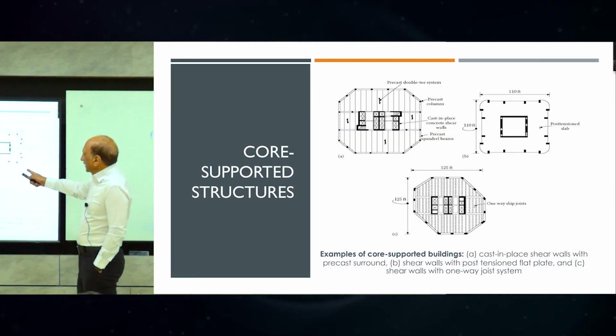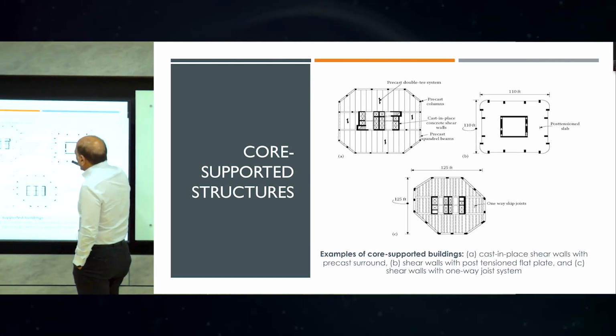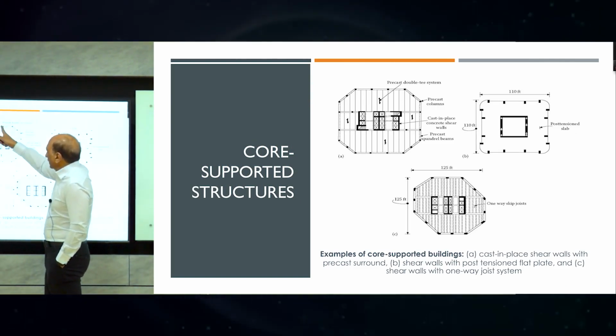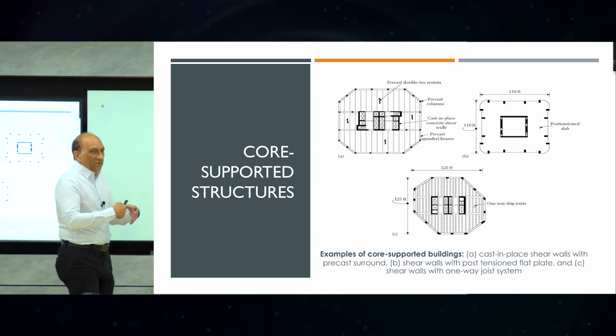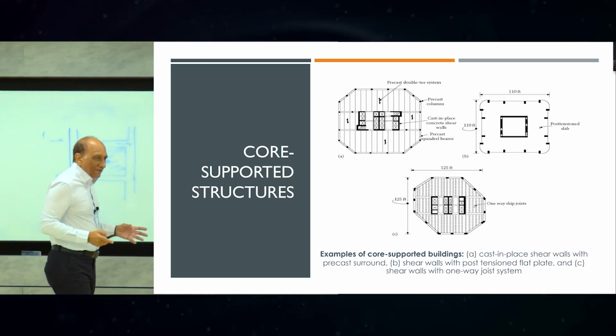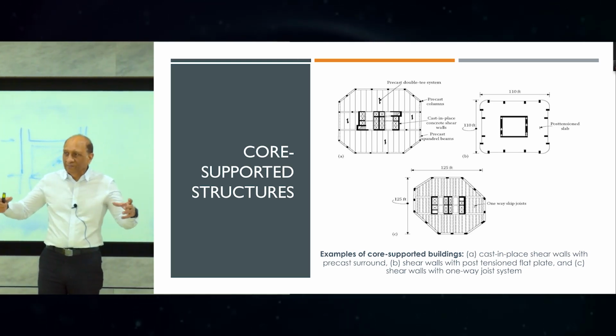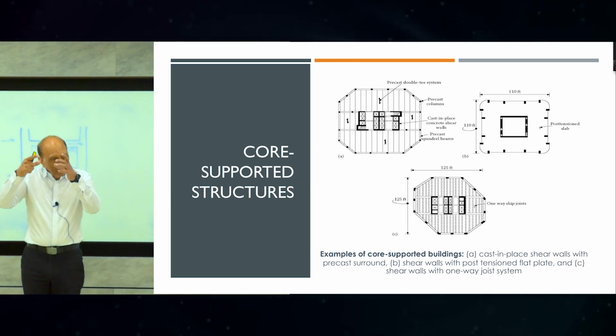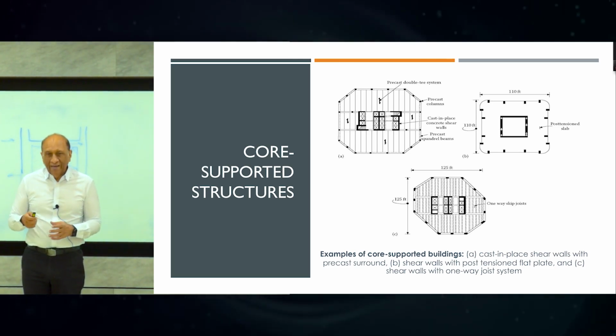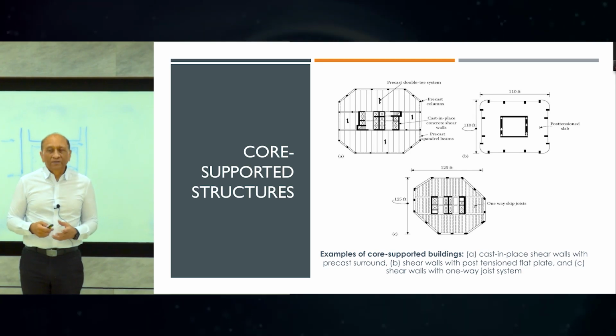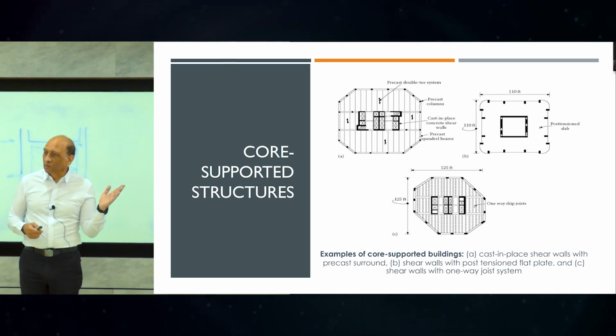And then we have the core. As I told you, core is very important. So there's a core wall, core wall, core wall, and around that column. Core wall is which contains the elevators. Around the elevators, you use that portion to create your main primary core. We talked about this quite a bit. And you use that core basically to carry the lateral loads.